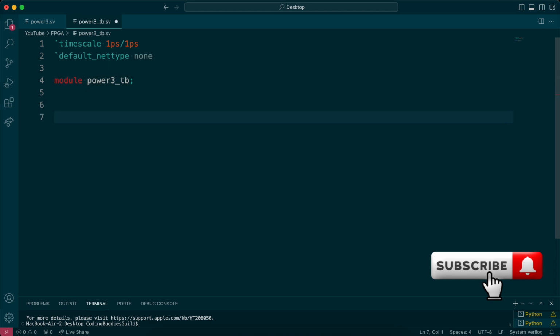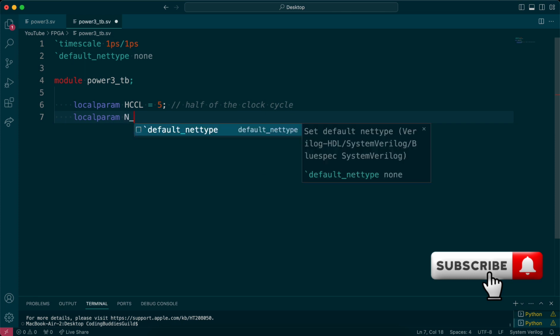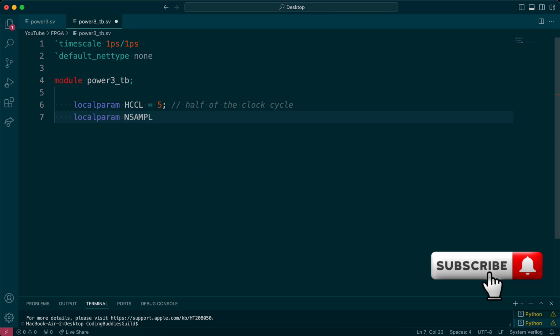Let's get started. We can go localparam HCC, that equals, let's say, 5. It's half of the clock cycle. And then again localparam, how many samples do we want to pass through? It's our test bench. Let's say number of samples, and we set that to, I don't know, 9 samples, for example.